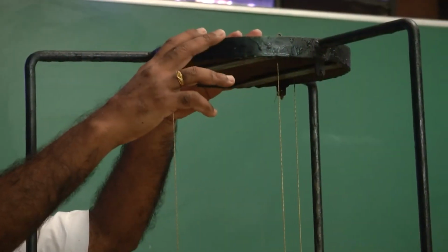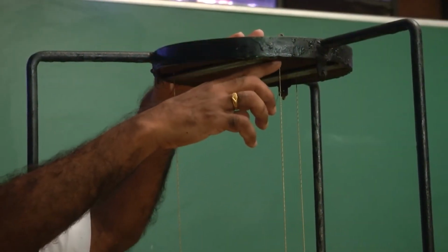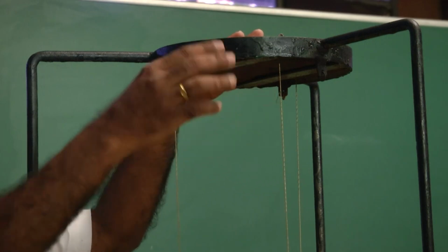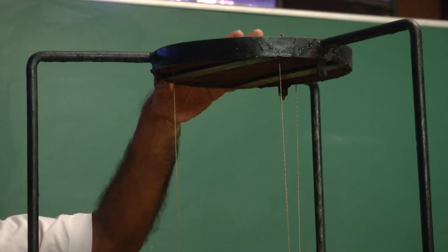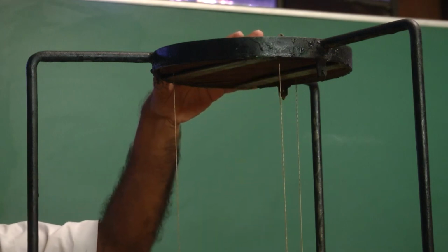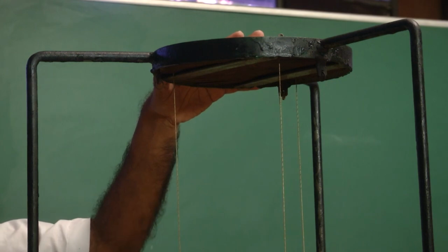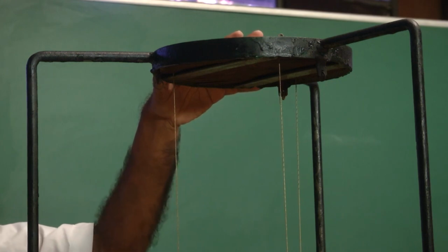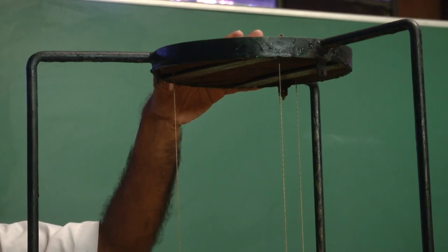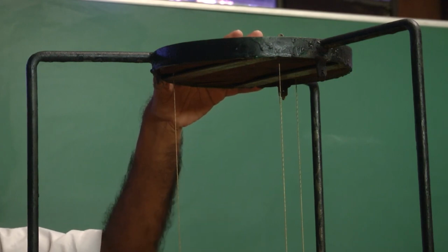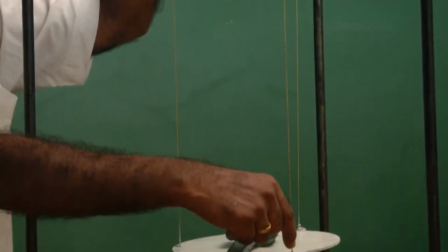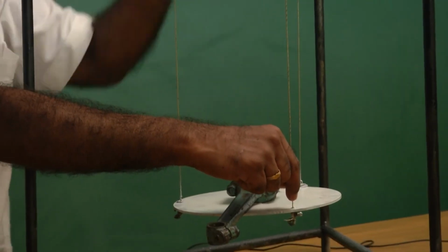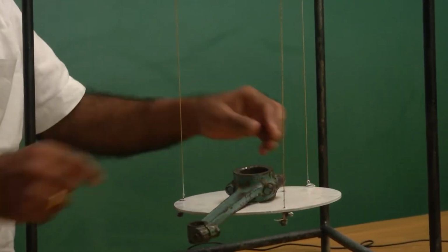So, this system has three strings which are fixed at three equiangular positions on this frame, and these inextensible strings basically connect the plate to the top frame, and these strings are exactly vertical at the equilibrium position of the plate, and it is only when the plate tries to swing about its vertical axis that the point of connection of this string with the plate changes its orientation. Okay. So, about the vertical axis, this is how it changes.